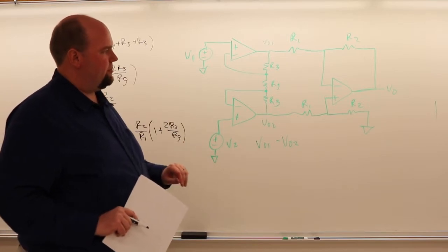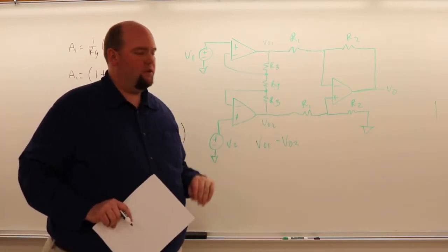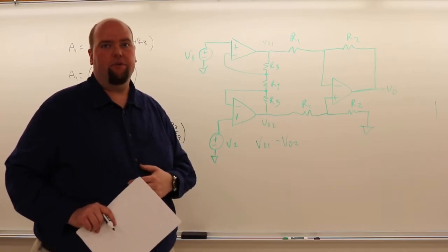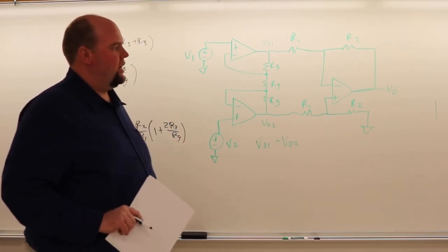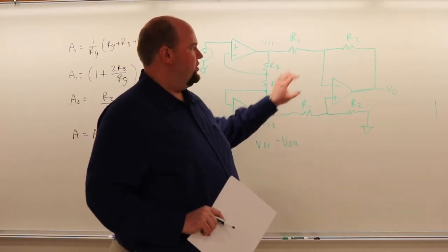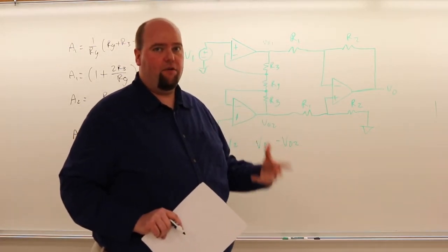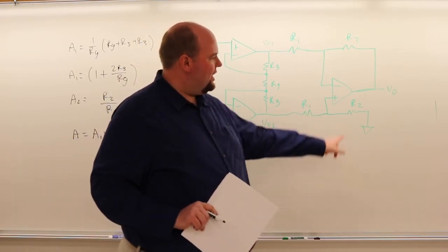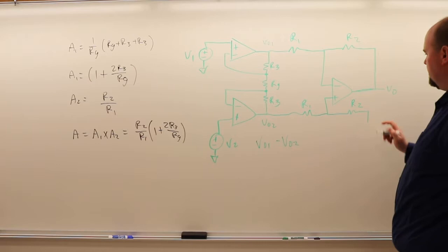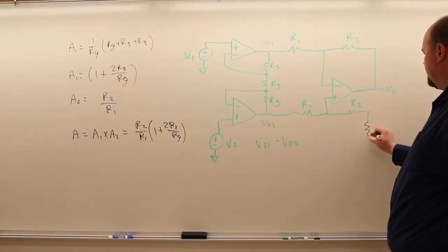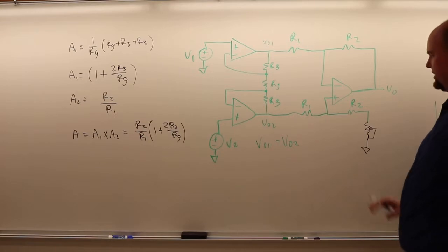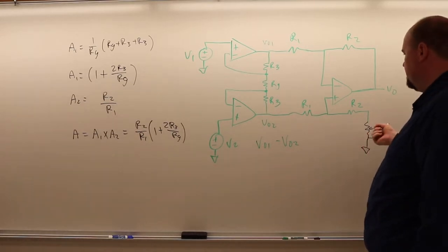In a very good instrumentation amplifier, not only would these resistor values all be balanced and trimmed from the factory, but they would also be designed internally to have compensation for changes in temperature, and to limit aging effects. Sometimes, though, manufacturers will say there's no way to guarantee that these resistor values will stay stable forever. So sometimes they will give you a little bit of access to R2, and instruct you to add your own potentiometer here and connect it to ground. That is one method that is sometimes used, and this allows you to trim this.